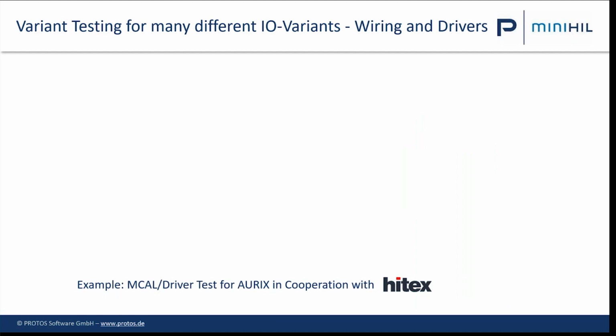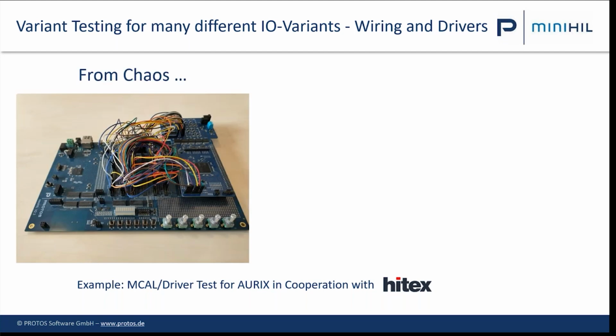So together with Hitex, we've developed MCAL and driver tests for Aurix processors. For example, for the AUTOSAR basic software stack and for the MCAL stack. And the first version looked like this, because for an MCAL test, you need all the combinations of all the IOs at every pin. That's a lot of wiring. An application level test is simpler to wire, but an MCAL level test, especially for ASIL-D, for high safety requirements, that's really hard to do from the wiring perspective.